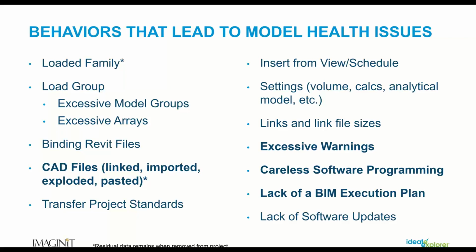And then last but not least on this one is a lack of BIM execution plans. If you have one of these in place, it's going to talk about your deliverables, the level of development that you're going to do, but also about how we're going to clean up the model and all the different processes that we're going to use and put in place. So a good BIM execution plan is going to help tremendously in the health of the model. As my friend Sash over at Ideate likes to say, remember that model health issues are typically a progressive,